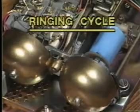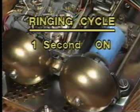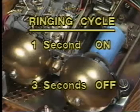To avoid a constant ring, however, the alternating current is repeatedly turned on and off to produce a ringing cadence. This is accomplished at the central office using a device called the ringing interrupter. In general, the ringing cycle takes about 4 seconds, 1 second on and 3 seconds off.